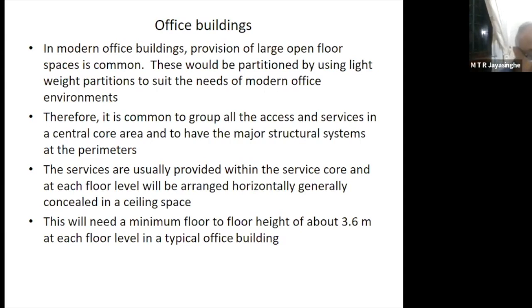So in apartment buildings, one of the options is above the transfer plate, you can have a large number of small concrete walls, thin concrete walls of 225 millimeter thickness or 250 millimeter thickness, and so many walls, which means you need a transfer plate structure, as I explained last time. On the other hand, there's another option. That option is use few large columns and have a large span, then a large slab.